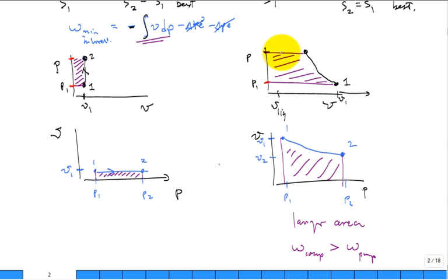Why do they put a solid line between states 1 and 2? Because it's an internally reversible process. If there are irreversibilities, guess what? I'd have to put a dashed line, and then I cannot interpret the area to the side of that curve as some minimum work. This only works if you have the internally reversible assumption.